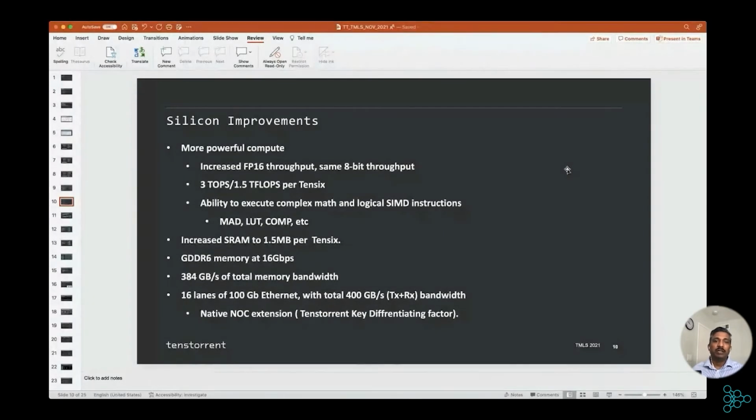More importantly, as part of this development, we have what is called a network on chip. It's an interconnect fabric which connects all our cores. I will give more details on why our NOC is powerful, but this is one of the key differentiating factors. This NOC allows traffic to move from one chip to another chip, and in fact any other configuration, very seamlessly, which is very important from the software point of view. You can build a mesh of cores, but you also want to make sure that from the programmer's point of view, it really appears like a mesh of cores without any overheads.